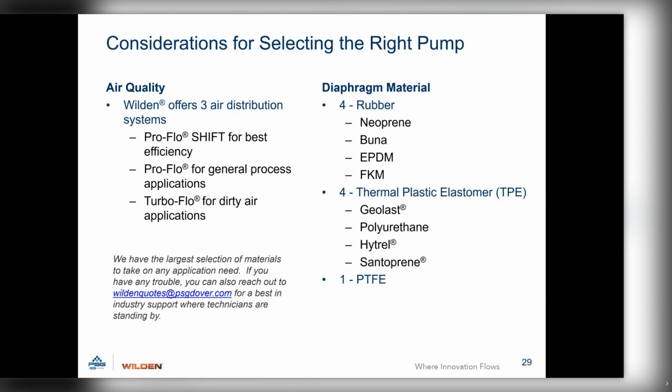That is our best thermoplastic elastomer diaphragm out there for pumping anything that is going to be abrasive. So if you want the longest life out there, you go with the Santoprene, and it's going to have a lot of the same chemical properties as PTFE, but a fraction of the cost. Think of it as a low-cost alternative to PTFE.